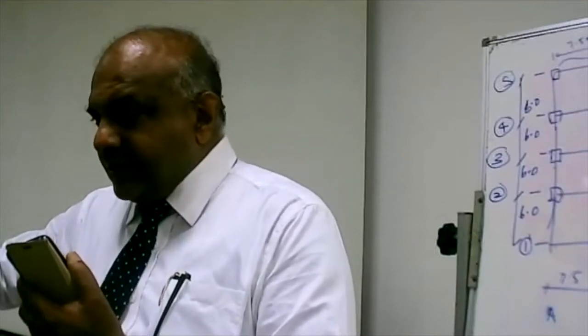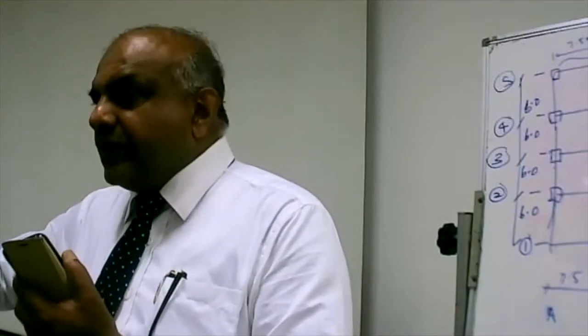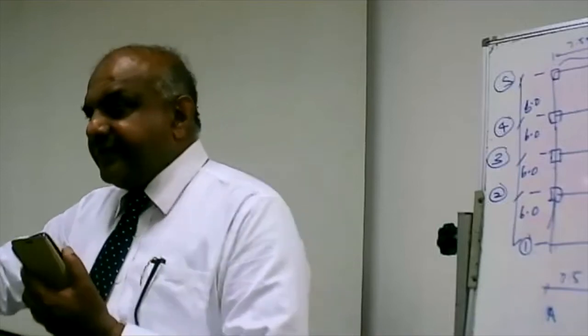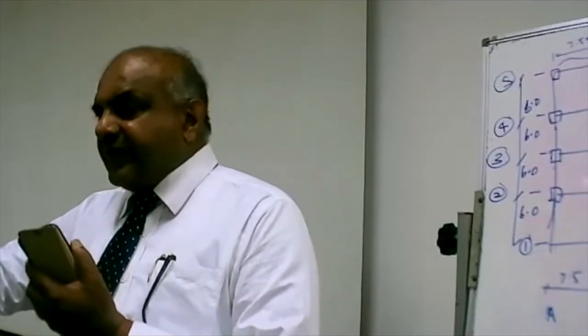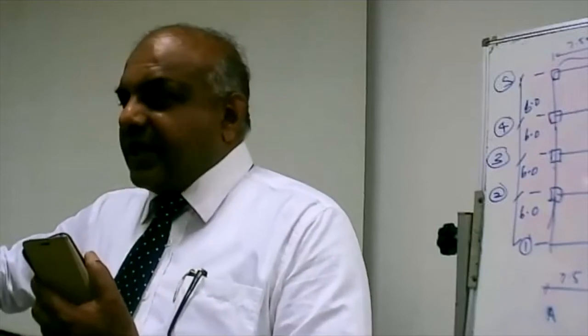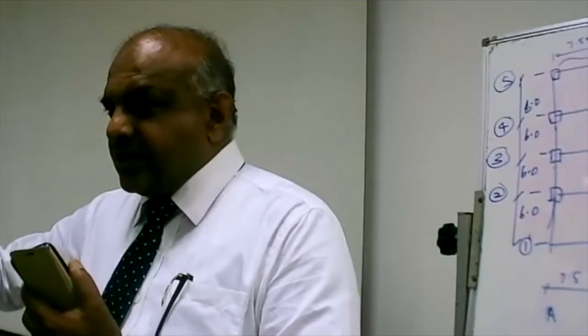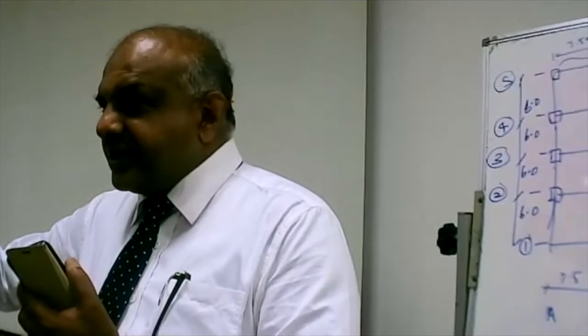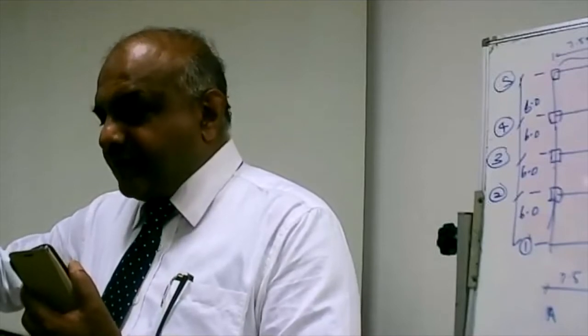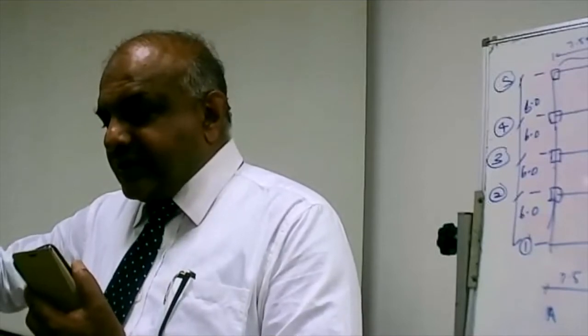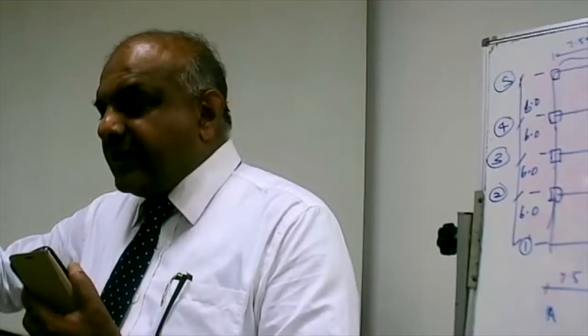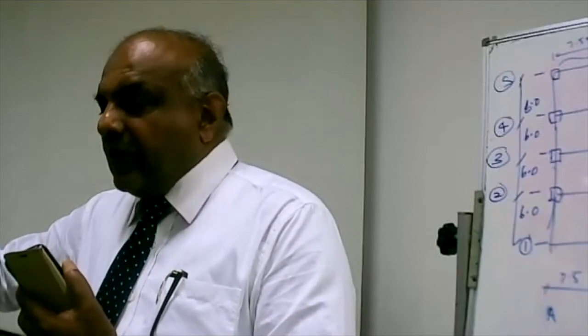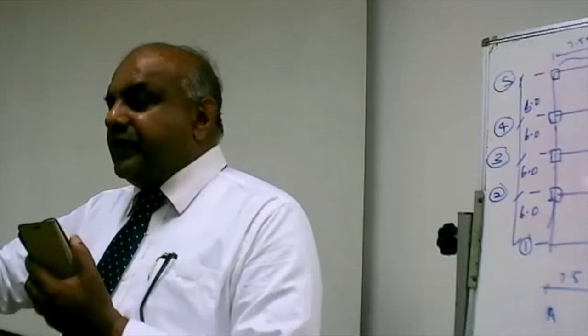0.15% of the dead load. But in the Eurocode also, a similar rule is given. So you have to use that rule and calculate the value. The values come closer, and always consider notional load. You have to consider the maximum of the notional load or the wind load. Whichever is higher, you will use it.